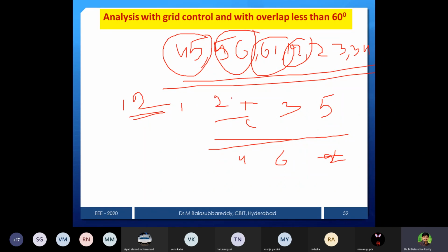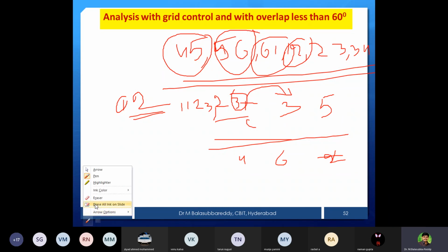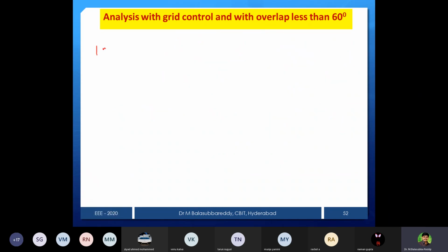In the normal case, 2 3 will fire, but now a changeover or commutation is going to take place: 1 is going to turn off and 3 needs to fire. Between that 2 3 case, we'll get 1 2 3, then 2 3. So is it clear? In between 60 degrees, after 1 2, there is the normal case 2 3, then 3 4, then 4 5, then 5 6, then 6 1, and so on, then 1 2.